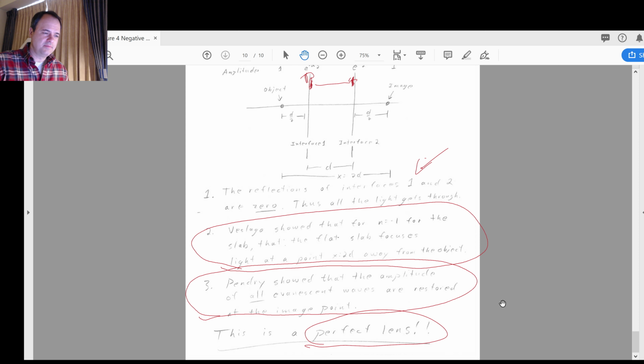And this, I mean, the metamaterial lens. Well, two things that have held up a lot of amazing metamaterial applications, and that is bandwidth and loss, and additionally fabrication complexity. So as we'll see in all metamaterials, you invariably have loss such that even though you may not have a lot of reflection here at the two interfaces, you have a general loss of energy as the beam goes through the material.